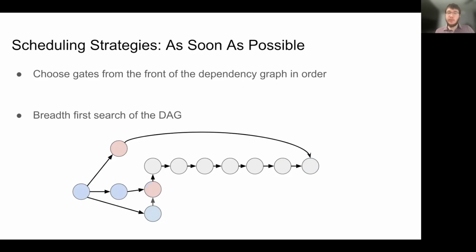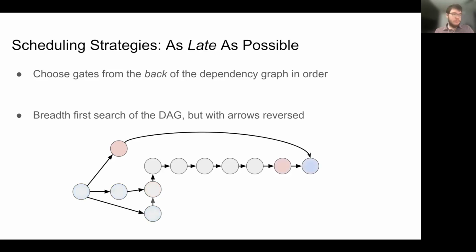When the scheduler has multiple choices, so for example, we had 3 choices at the very beginning, different heuristics can be used to choose. For example, we may prefer to choose operations along the critical path so that we can guarantee that that path will be executed quickly, which is going to be the longest path in our circuit anyway. A very similar strategy is to execute as late as possible, ALAP. This simple strategy starts with the end of the circuit, with that inf node at the end, marked in blue, and schedules the last gate needed to be completed, and goes backwards from the previous gates.